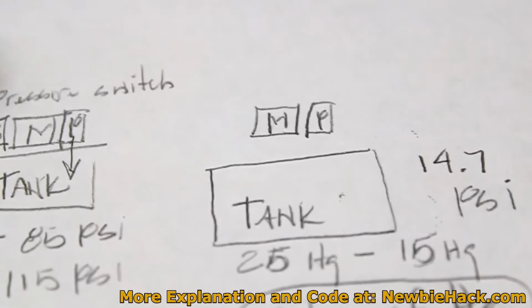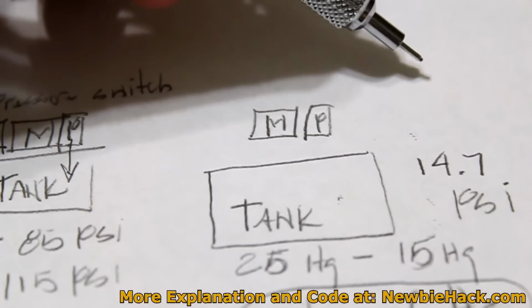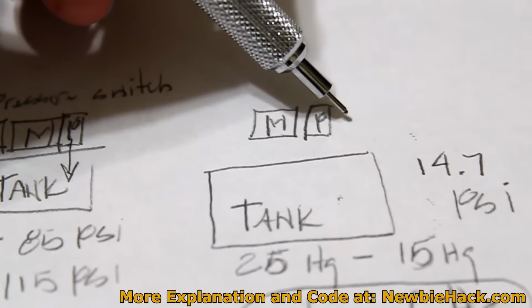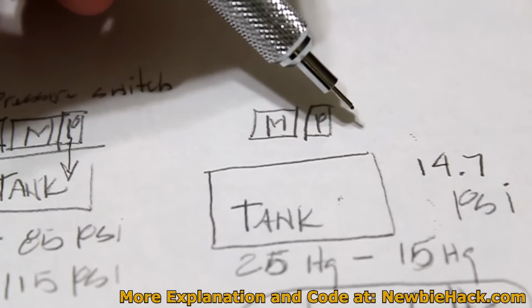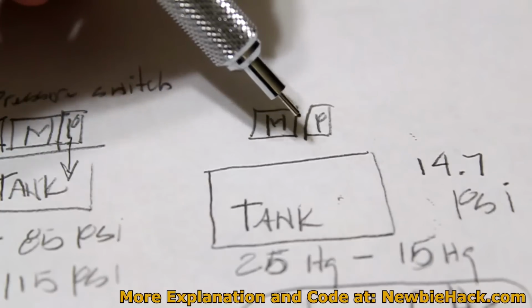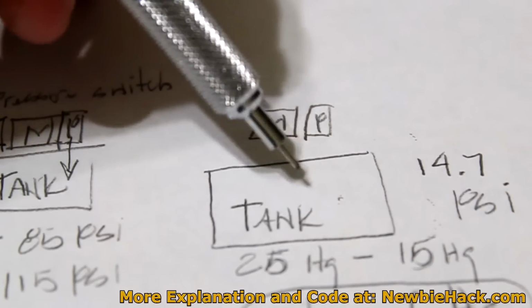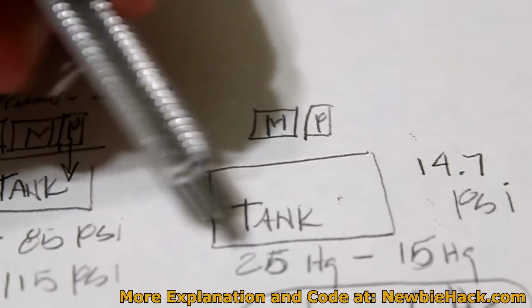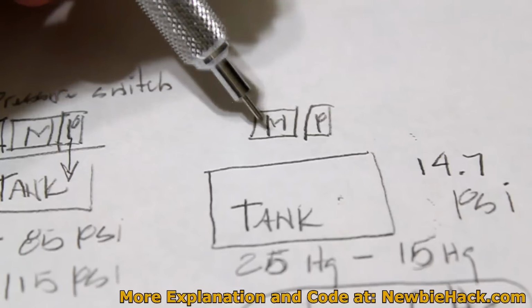I could just use the motor and pump as a vacuum pump, and just continually run it and use that as a continuous vacuum, but there's really no sense in wasting valuable pumped air, which is valuable vacuum. It's good to use a tank to save the efforts of what the pump is doing.